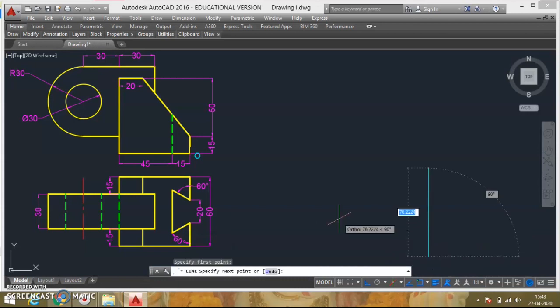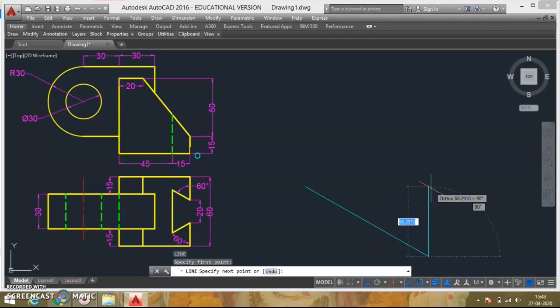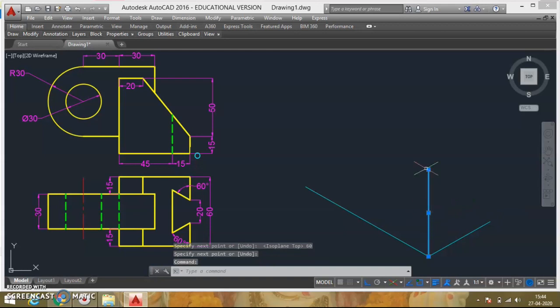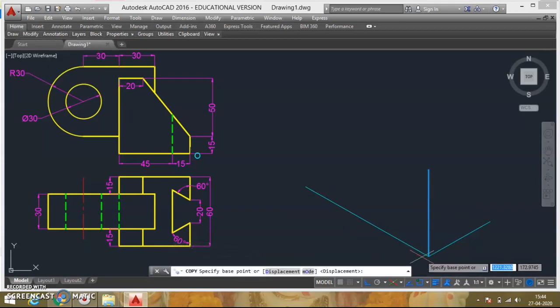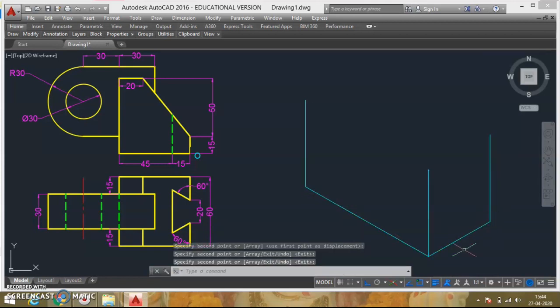So from this side 120, then height 75, then breadth 60. Once it is done, then what next we'll do, we'll draw a parallel line to this line passing through this point and this point. So you can use the ruler scale through which you can draw these parallel lines like this. Then you can measure this distance of 75, and mark it on this side